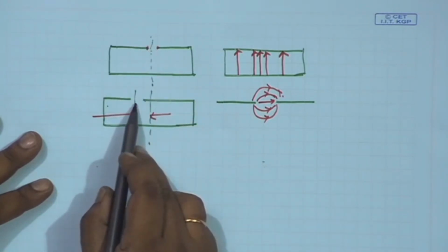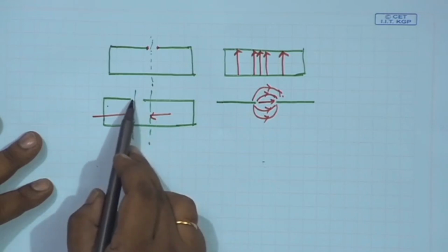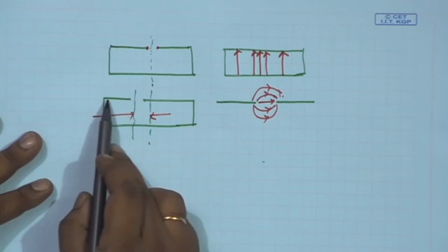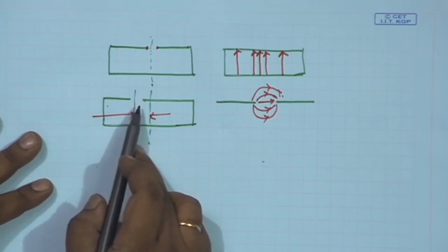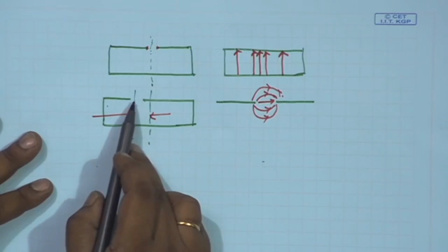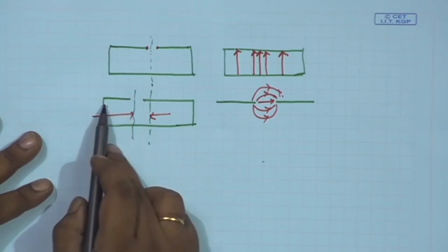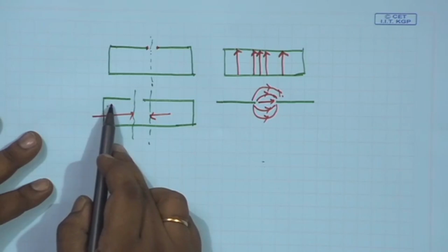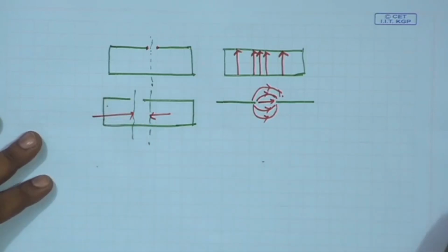But when we use some offset, then the input impedance changes, and this change is maximum when we place the slot near the side walls. So, the final placement of the slot will be a compromise, because we have two opposite behaviors: when we place the slot near the side walls, we will see maximum input impedance mismatch, but maximum radiation from the slot.